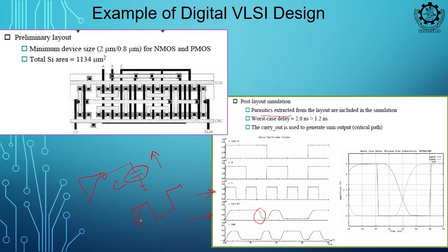It will be difficult to drive this node, isn't it? Capacitance follows the exponential nature, right. So, if this C value keeps on increasing, your RC time constant is also increased, right. So, it will take more time to charge it up, right. So, it will be exponential, it will be delayed.